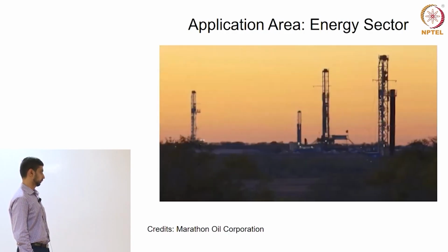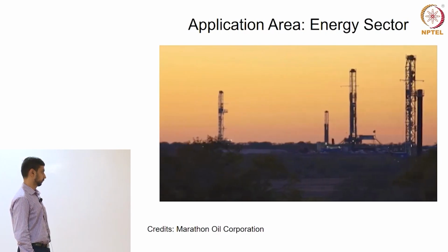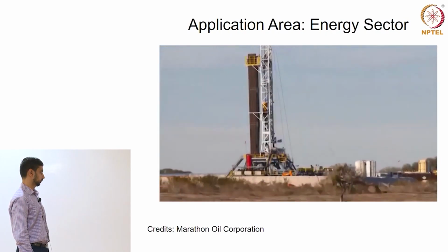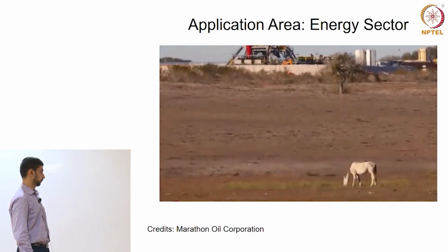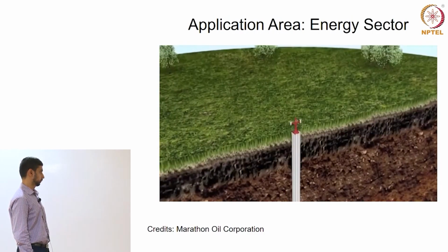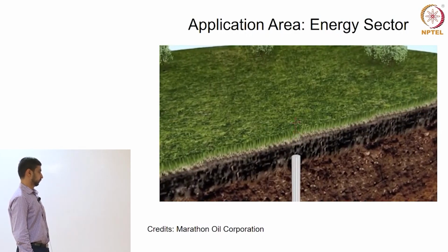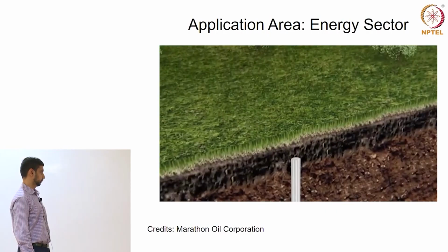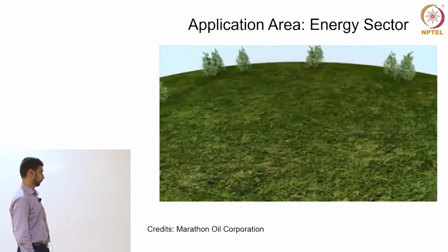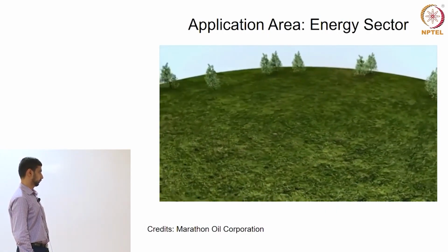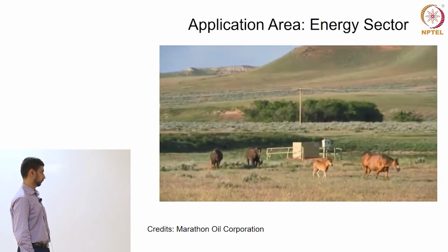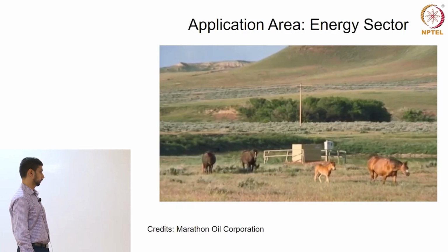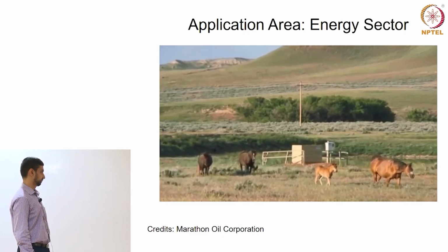When all of the oil or natural gas that can be recovered economically from a reservoir has been produced, work begins to return the land to the way it was before the drilling operations commenced. The well will be filled with cement and pipes cut off 3 to 6 feet below ground level. All surface equipment will be removed, and all pads will be filled in with dirt or replanted. The land can then be used again by the landowner for other activities, and there will be virtually no visual signs that a well was once there.